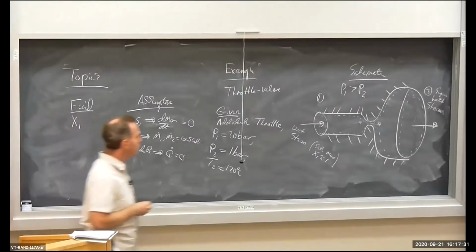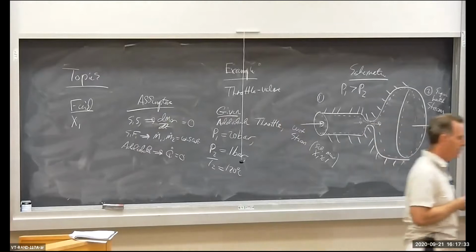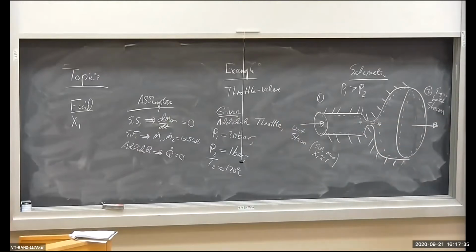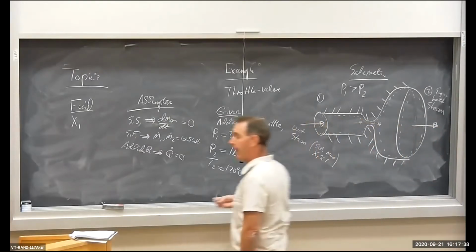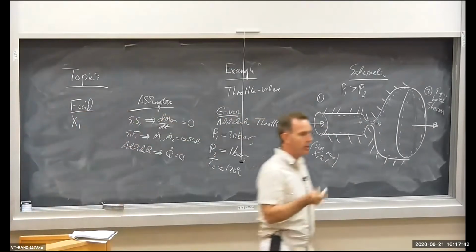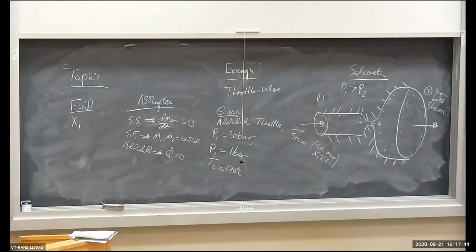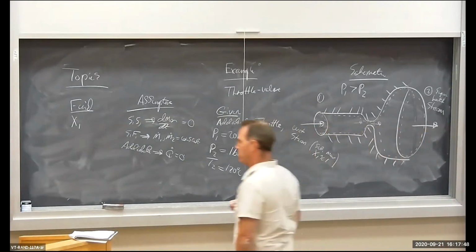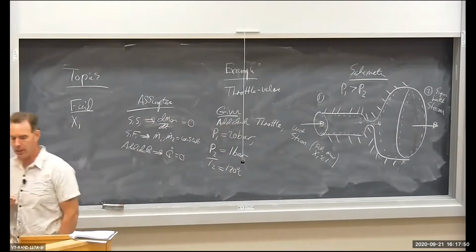What about W dot, the work term? Remember, in the open system energy balance, W dot has 3 components: boundary, shaft, and electric. The pressure power has been absorbed into the enthalpy term. The m dot terms in the form of enthalpy. The U became an H.